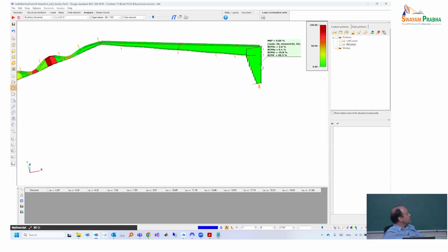If I activate, for each of the buckling modes which were calculated, we perform the creation of this map for the distribution of the deformation energies, and we assign a given buckling mode to the member which produces the maximum, obviously the 100%, so there's no hesitation, that will be assigned.